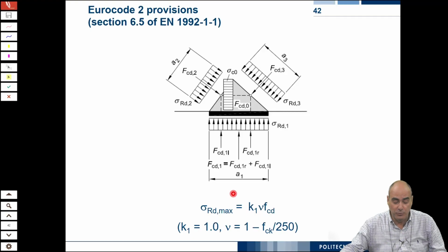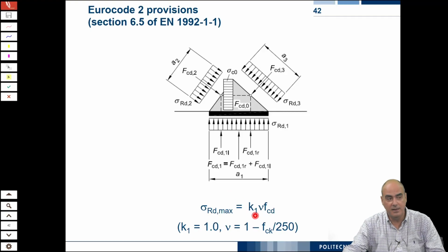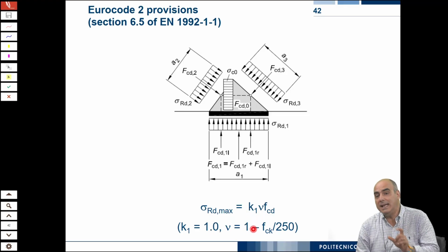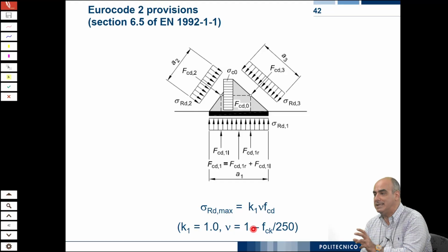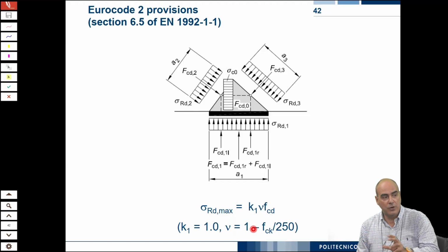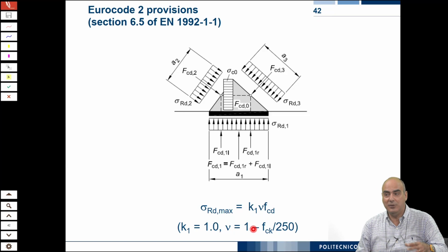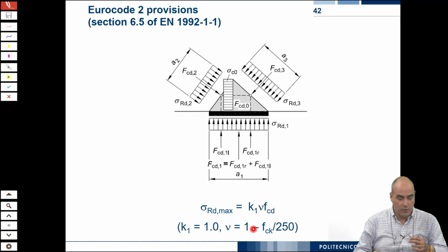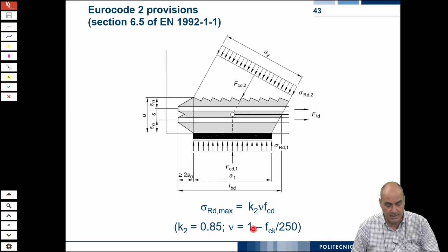But still, in the code we are a little bit cautious: we do not take into account the benefits from a multi-axial state of stresses, and we still apply the brittleness reduction factor. For higher strength materials under triaxial stresses, at a certain point your concrete really crushes down, it pulverizes. We take this into account. This is, for example, a CCT node.